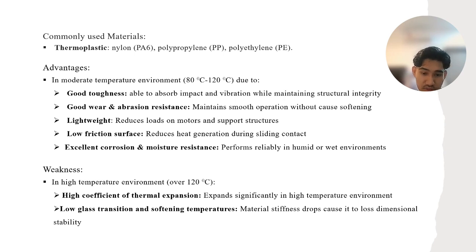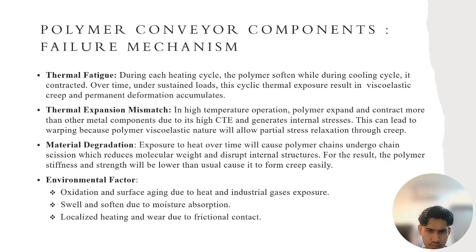Weakness in high temperature environments over 120 degrees Celsius: high coefficient of thermal expansion, expanding significantly in high temperature environments. Low glass transition and softening temperatures, meaning material stiffness drops and it loses dimensional stability. So the failure mechanism for polymer conveyor components.